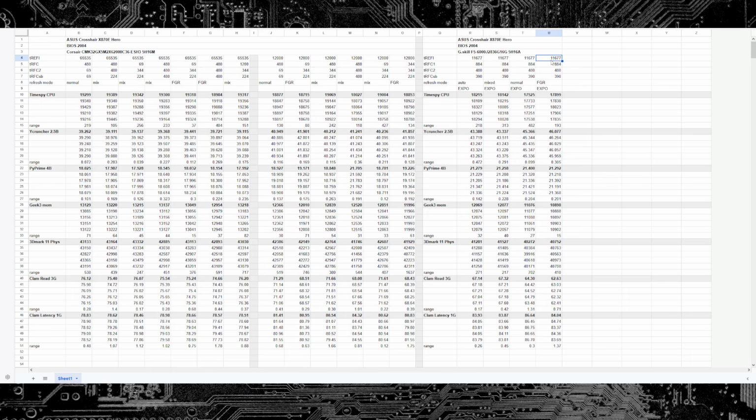horrendous. And that's because it's refreshing far more frequently. It's just that you're more likely to get lucky and have accessible banks with FGR mode, whereas with normal mode, it's, nah, the whole thing gets blocked. Anyway, so that's kind of the difference. FGR skews towards latency, and normal mode skews towards memory bandwidth. But once the refresh interval gets a lot higher, these differences kind of level out.